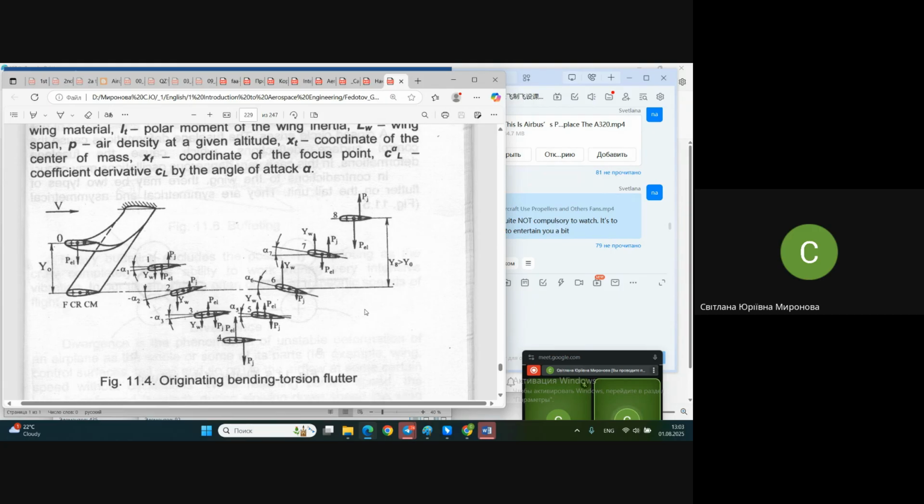Unloaded elements in the structure are thinned, or removed altogether in case they do not take part in receiving and counteracting loads. They are not necessary in aircraft structure because, as we remember, we are obsessed with minimum weight. Minimum mass of the airplane is the first ever rule that we should follow too.